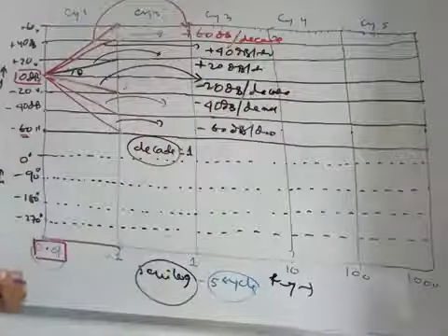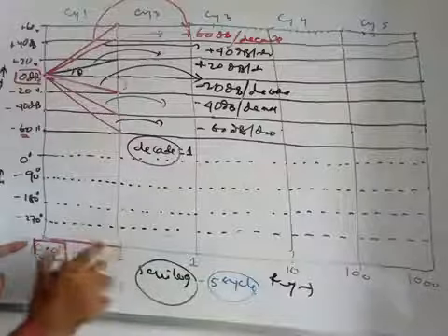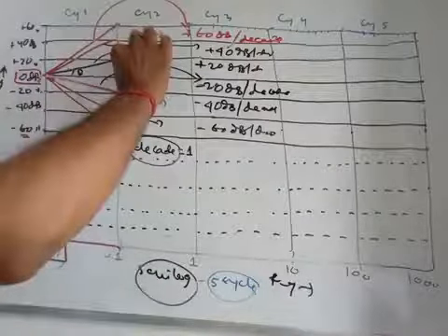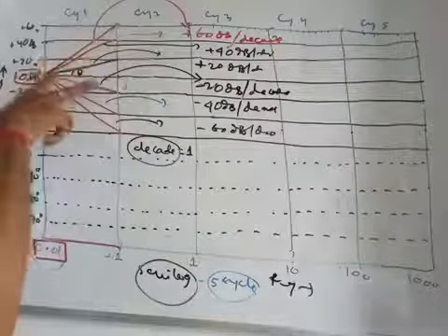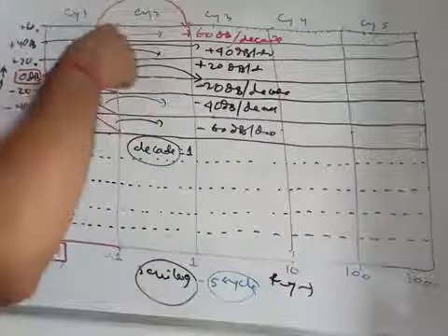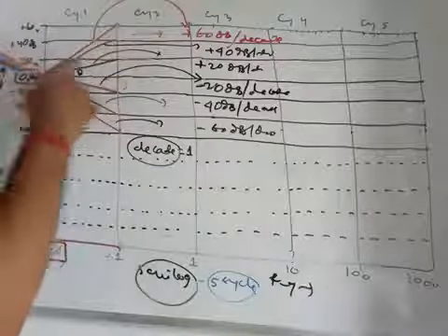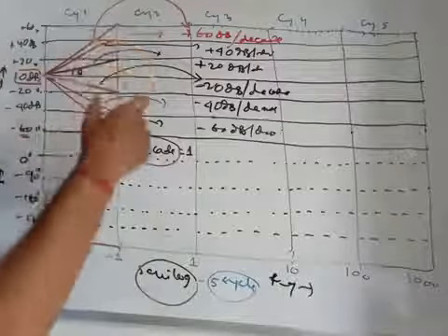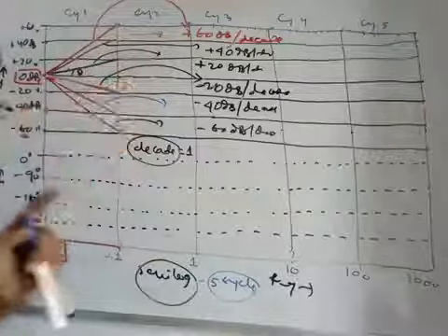That means in each case the change in frequency is 1 decade. So this is your tan theta. Tan theta means the y-axis change and x-axis change. Change in y-axis means initial value to final value, that means 0 to plus 20. So change in magnitude is plus 20 dB, and corresponding change in x-axis is 1 decade.